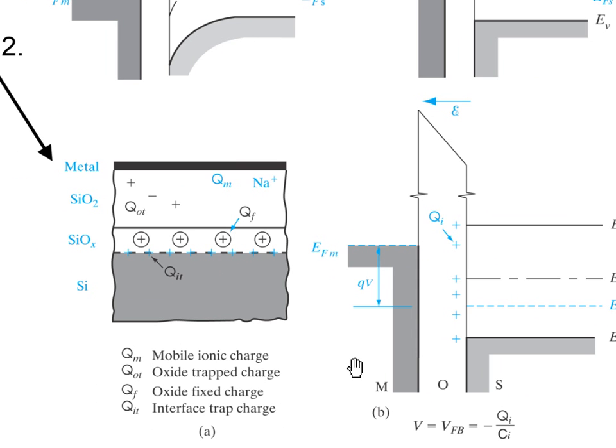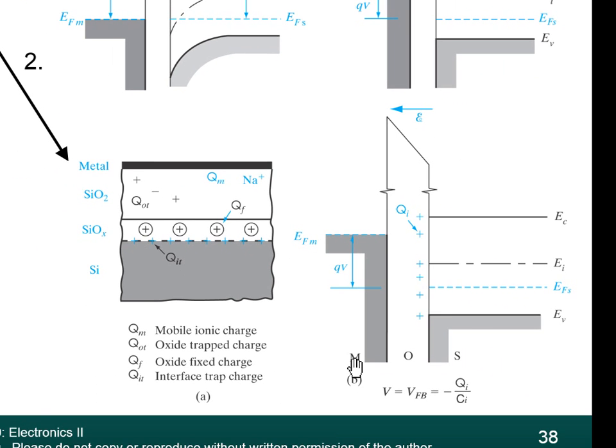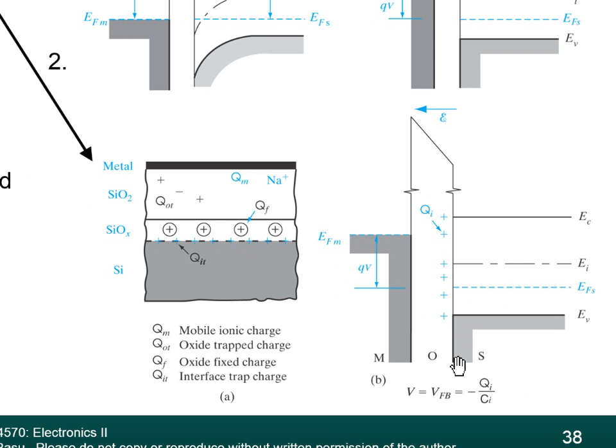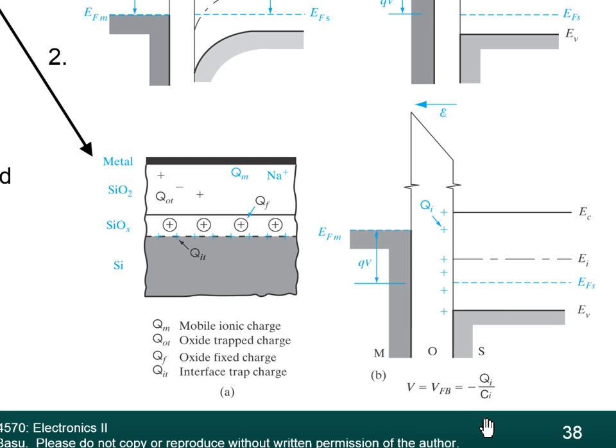This is one of the very challenging problems in fabrication, because if one day you had dirty water, well, that would change all the threshold voltages of your device. Huge problem. So that's why clean rooms use very, very pure deionized water to prevent this type of problem from happening. And that's why they prefer using dry etching over wet etching.